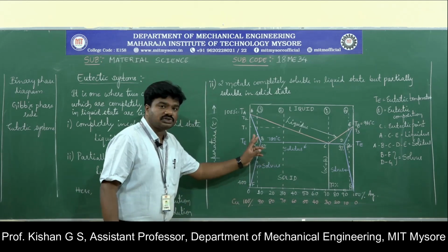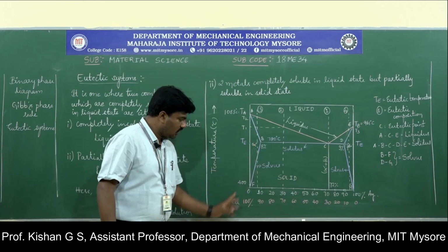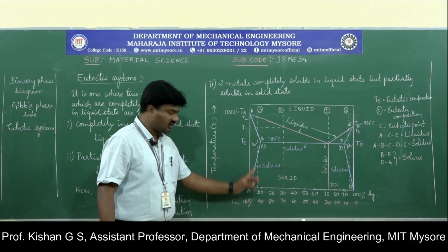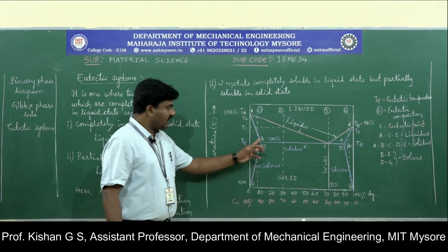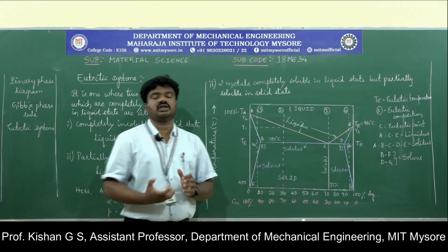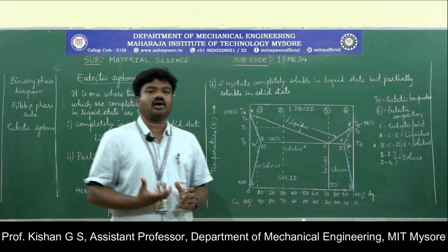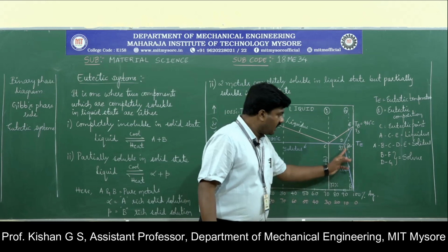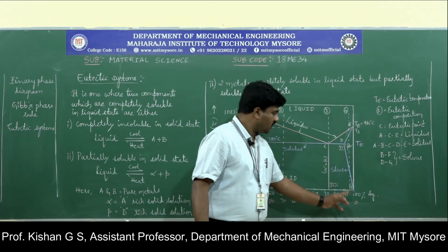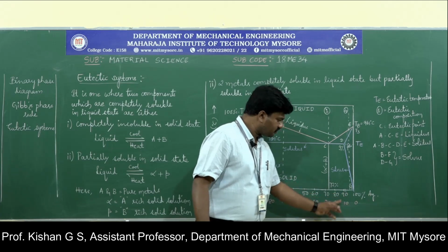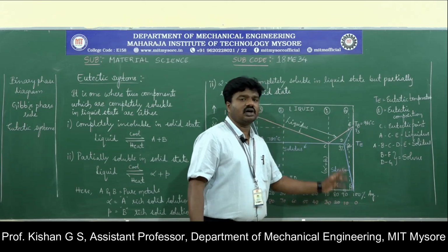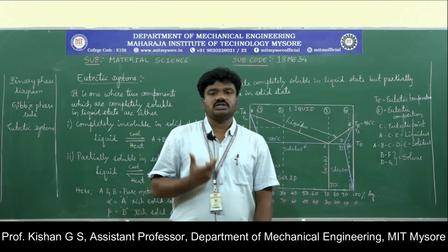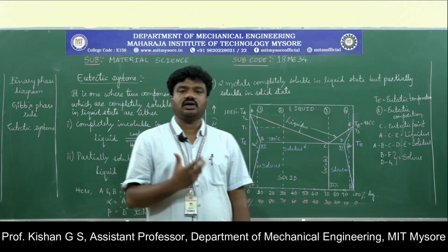So when the composition of copper and silver goes to 8% of silver with 92% of copper, there is a particular point below which the rich mixture of material A, or the rich mixture of copper, is considered. Similarly, for around 9% of copper with 91% of silver, you are going to get the partial solubility of B, that is material silver here, the silver-rich solution in consideration.